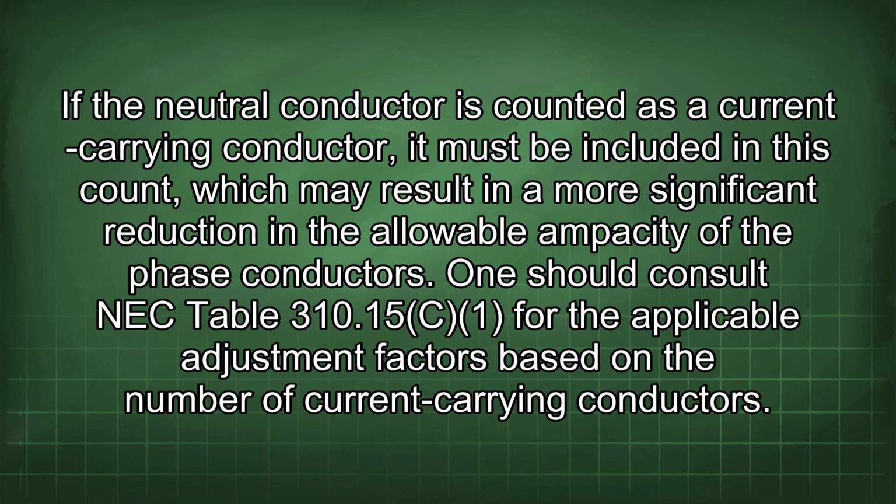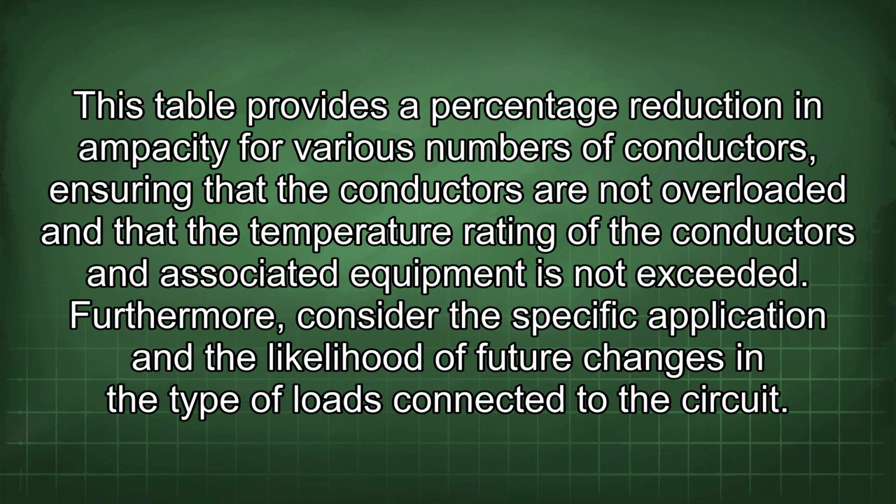One should consult NEC Table 310.15 for the applicable adjustment factors based on the number of current-carrying conductors. This table provides a percentage reduction in ampacity for various numbers of conductors, ensuring that the conductors are not overloaded and that the temperature rating of the conductors and associated equipment is not exceeded.